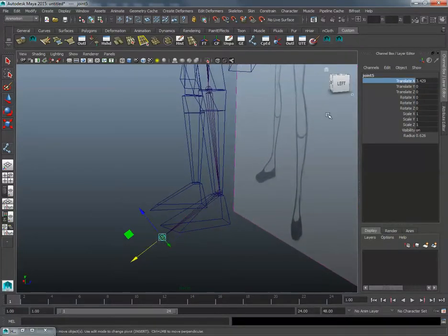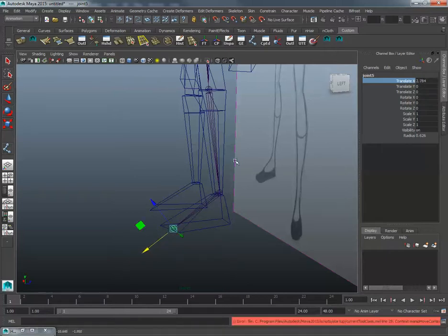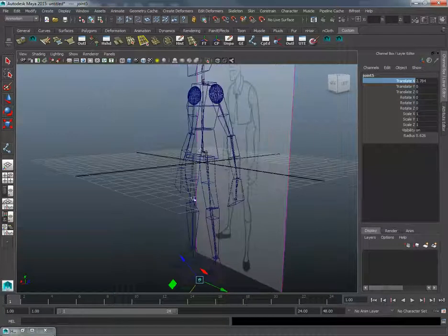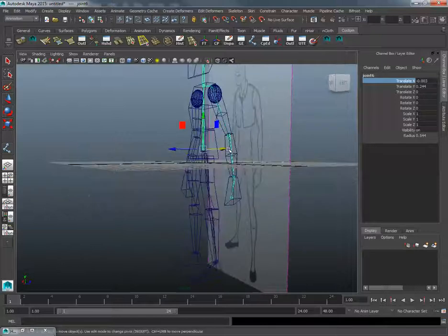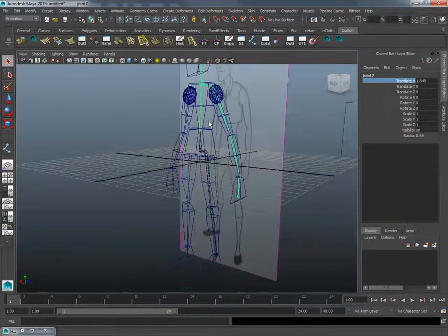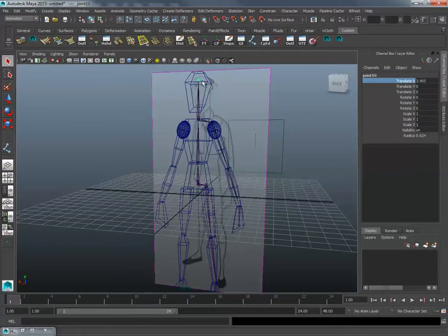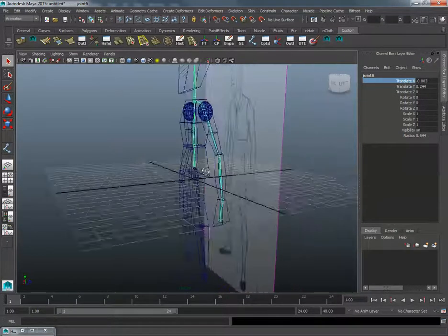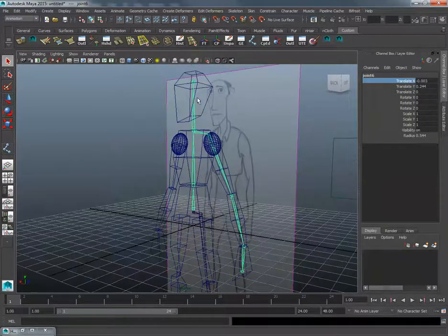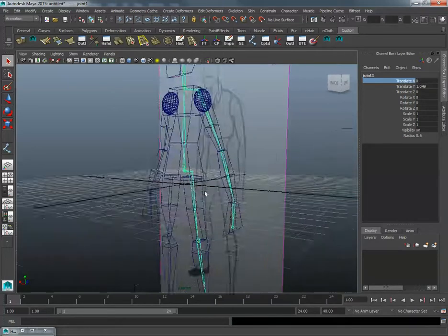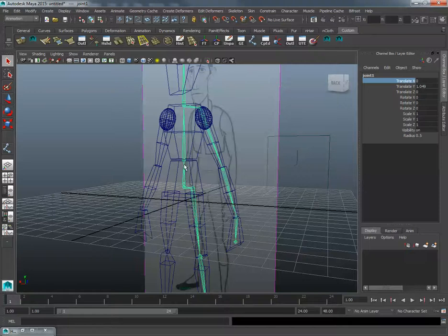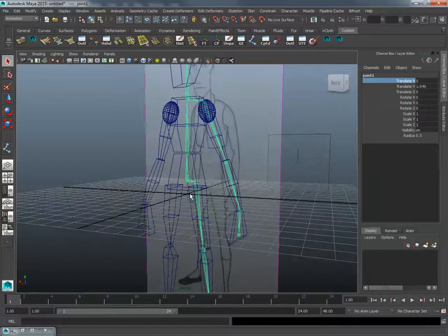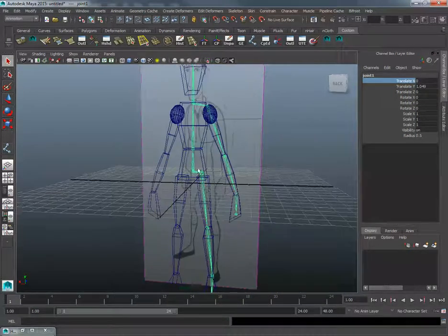And just going to move my toe to the end there. That's it. So I've got my skeleton. If you're using a skeleton, if you want to move up the hierarchy, and this goes for any hierarchies, and a skeleton is just the same as anything else, you can click on any part of it and just click up, and it'll move up the hierarchy until it gets to the top. And that's why it's just a bit easier than trying to search around and find out where the main parent is. So create the skeleton.